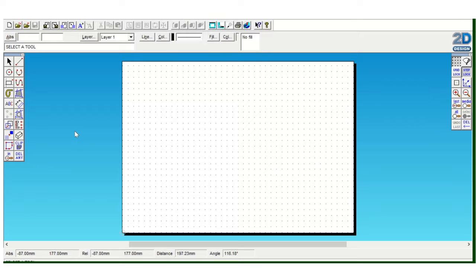We're going to make the small ruler here by using 2D Design, and we're going to make sure first of all that grid lock is on. Then we'll go over here to the left hand toolbox where we've got the shapes feature, select shapes, and as you come over from the dots here, dot to dot, the cursor snaps. That's the difference with having grid lock on compared to not having grid lock on. It doesn't snap. Go back to grid lock.